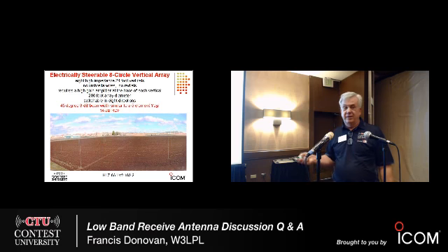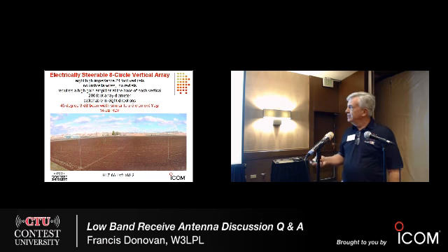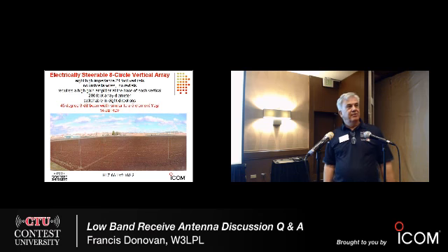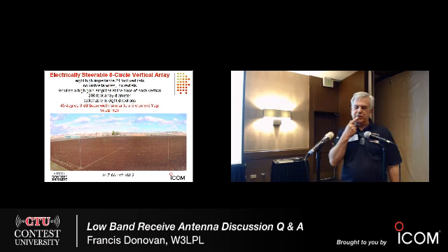So this really needs to be several hundred feet from nearby objects, otherwise it isn't worth the effort of putting it up. But it's pretty straightforward. No umbrella wires, no radials, 8 high gain amplifiers, one at the base of each vertical. And its performance, if you ever use an antenna like this, is just like using a large 5-element Yagi on 20 meters. Turn this antenna, the increments are every 45 degrees, and I've described my first experience using one